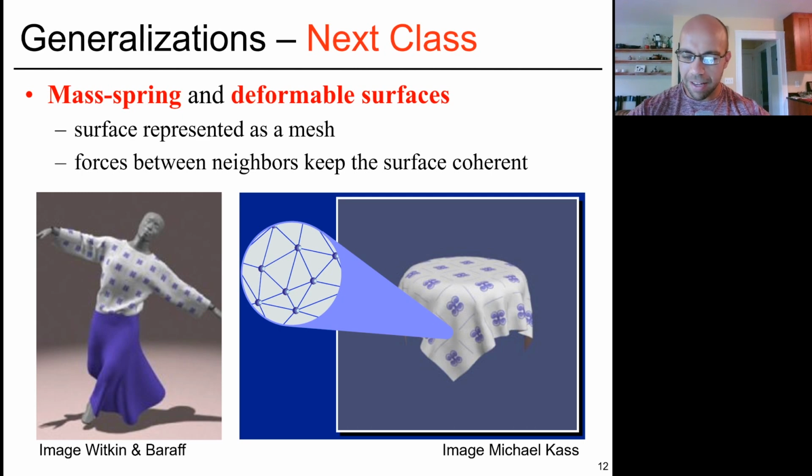We're going to start with the simple stuff today, and then in our next class, we're going to show how if you have a piece of software for a particle system, you can use it to set up a simulation of a piece of cloth. The way that we're going to do that is we'll think of our cloth, if you zoom in close enough, like a triangle mesh, just the way that we've done in our previous assignments in 837. And essentially, our proxy for our cloth not wanting to deform too much is to take each of the edges of our triangle mesh and think of them like little springs that are attaching to one another. And so by simulating these vertices coupled by springs moving together in time, you actually get really plausible, nice looking cloth simulation like what you see on this slide.